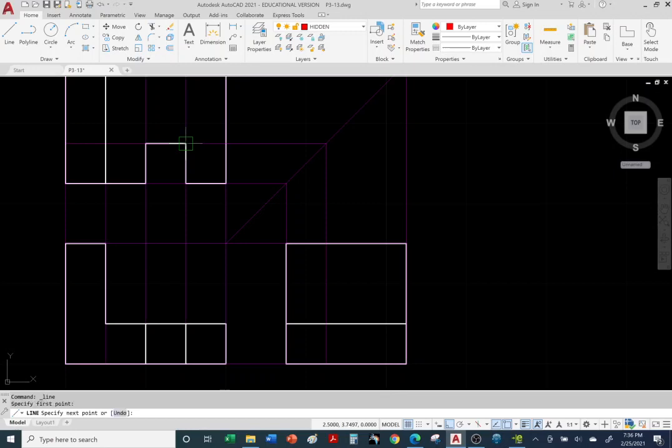Okay, so we're going to project. So I'm going to do some extra work. I don't need this red line, but I'm going to show you where this vertex lines up with the red hidden line on the side view. So you go across here, you hit the 45-degree angle line, click, and you go straight down, and that's where it's located, right? So we're using the construction lines, the magenta construction lines. Click. There it is. And I'm going to hit escape to exit.